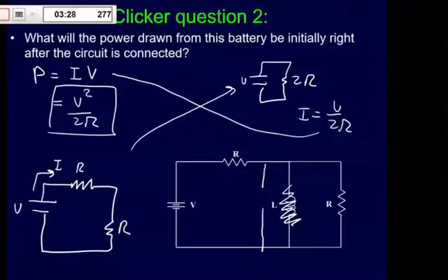So this is good too to say that unless we say otherwise, you assume the inductor is a wire with essentially very, very small resistance. And so at a long time later, that L would just be like a wire that would short circuit that R, okay? And then you just would have the circuit with the V and the R some long time later. So again, you can interpret the long time before and the long time after with more complicated circuits by thinking in this way.